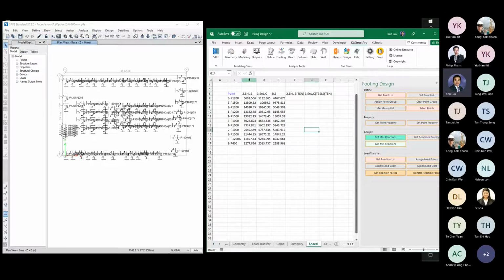Another way, sometimes if you want to do this one is for the piling schedule. Okay, other times, let's say you want to do some anchor bolt design for the column direction. So you have to get more of the results, let's say the moment and the axial load.